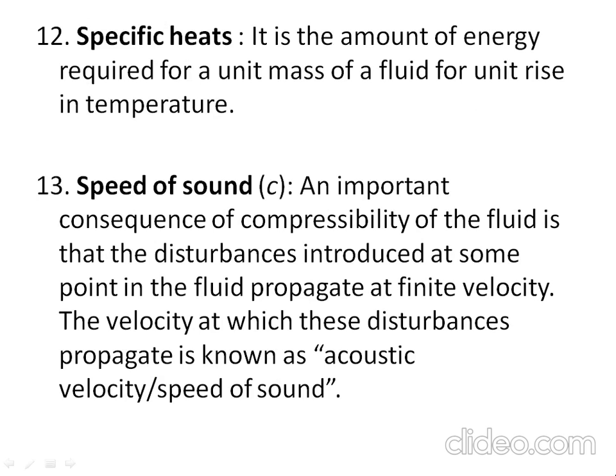And the last property is speed of sound. An important consequence of compressing a fluid is that a disturbance is introduced at some point in the fluid. So it propagates at finite velocity. The velocity at which this disturbance propagates is known as acoustic velocity or speed of sound.